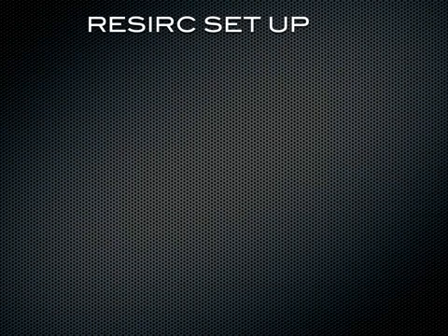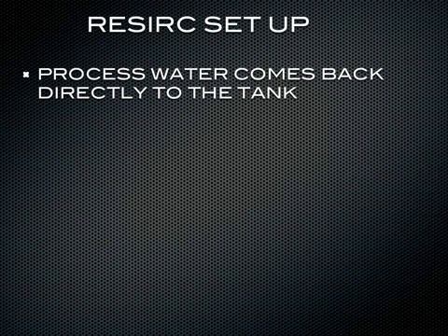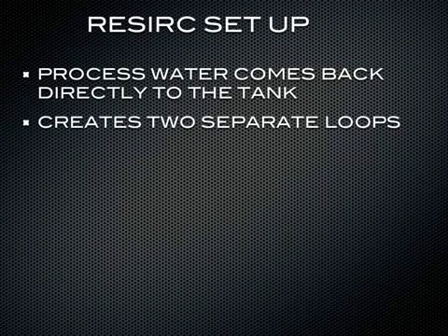Now, a recirc tank setup is where the process water comes back directly to the tank. On a once-through chiller, the fluid will come back directly to the chiller evaporator. In the recirc setup, it creates 2 separate loops.